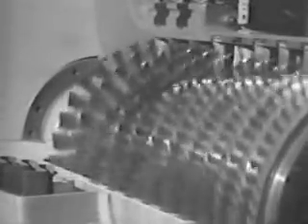The work of compression is done by several rows of blades, similar to the blades of an electric fan. Looking closely at these blades, we see that some blades are in stationary rows attached to the case. These are called stators. Other blades are in rows attached to the rotor assembly. When the rotor assembly rotates, these blades move much like a fan. These blades are the rotors.